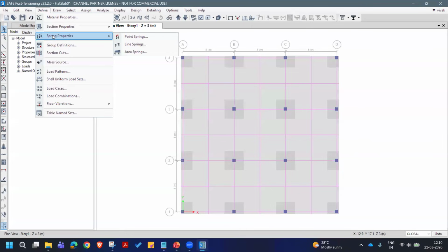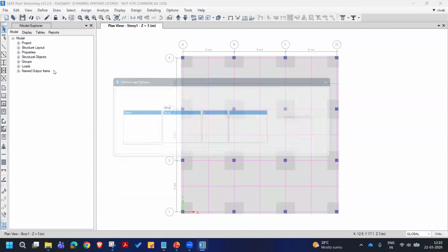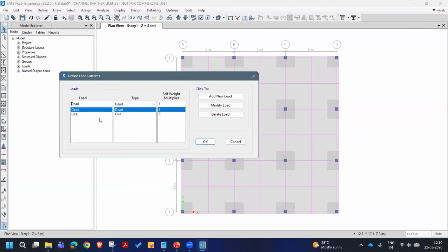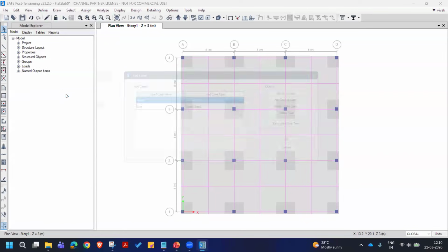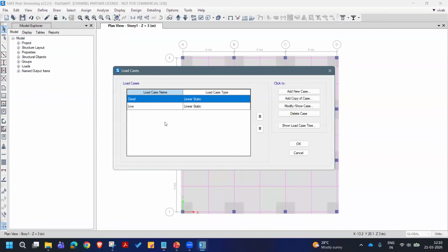All right. And all the loads are applied through the load patterns. So you'll see this list populated based on the load patterns available in the ETABS and exported here. And load cases for each of them will be automatically included. So the program handles this load transfer in two ways. One is the load pattern that exists here and all imported in another set.